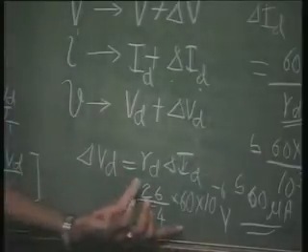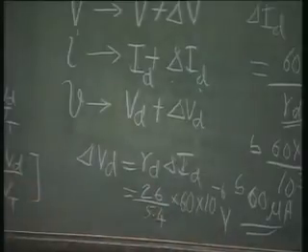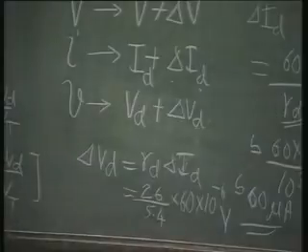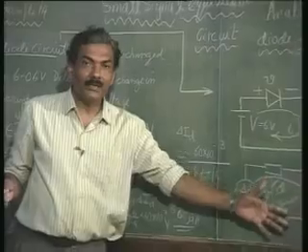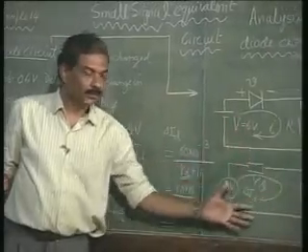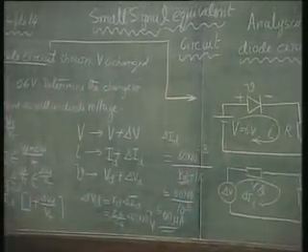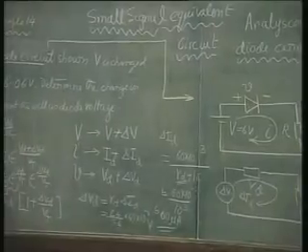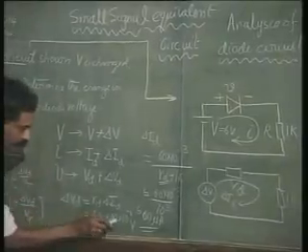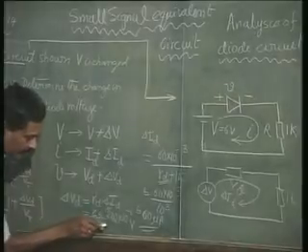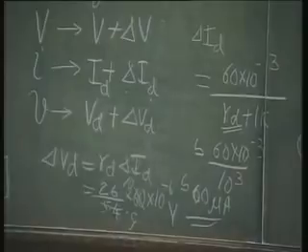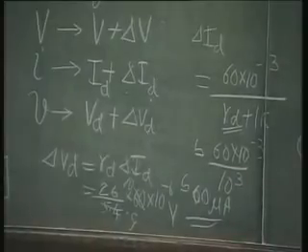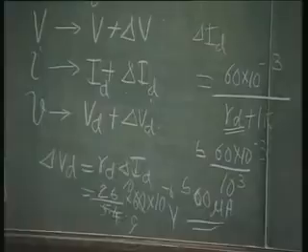Such is the accuracy of this small signal analysis that you are able to find the change, which is going to be extremely small, very accurately by this method of equivalent circuit for the diode. That change is fairly accurately evaluated here as, this is 10 times, this is 0.9 times. So this is around 260 divided by 0.9 microvolts.